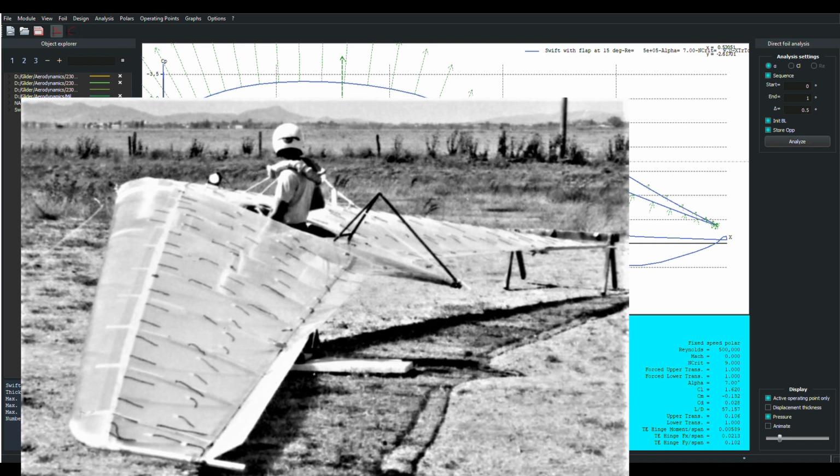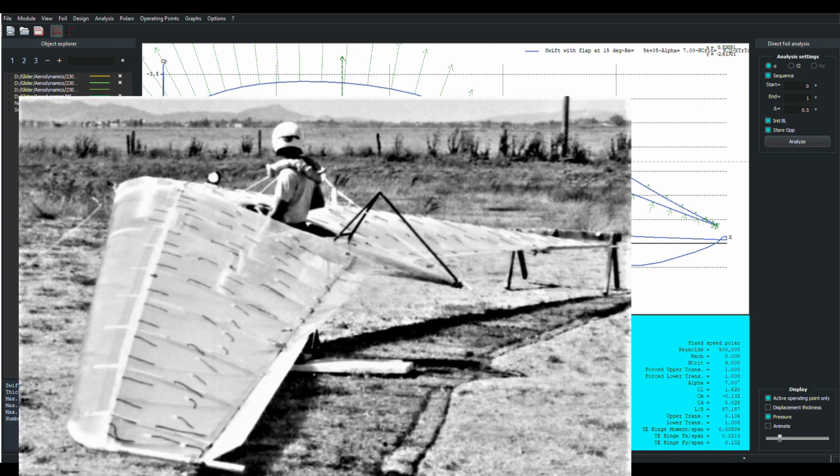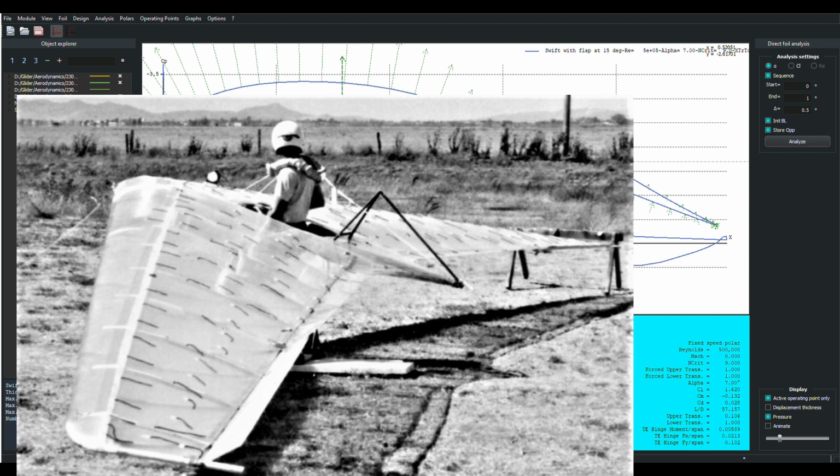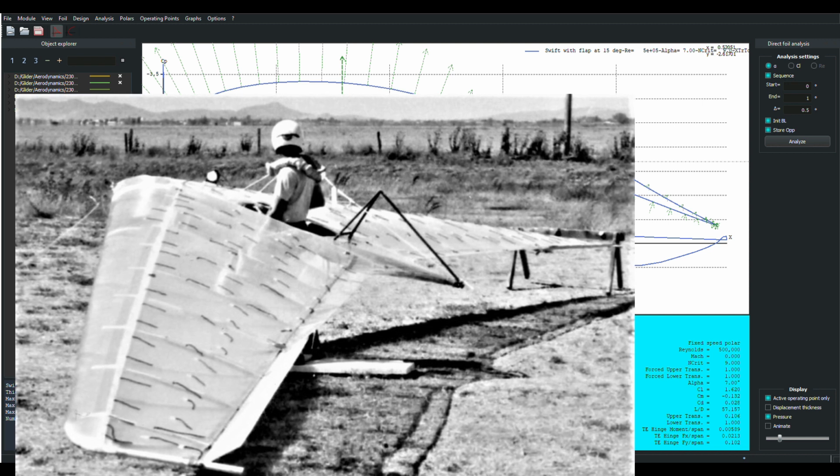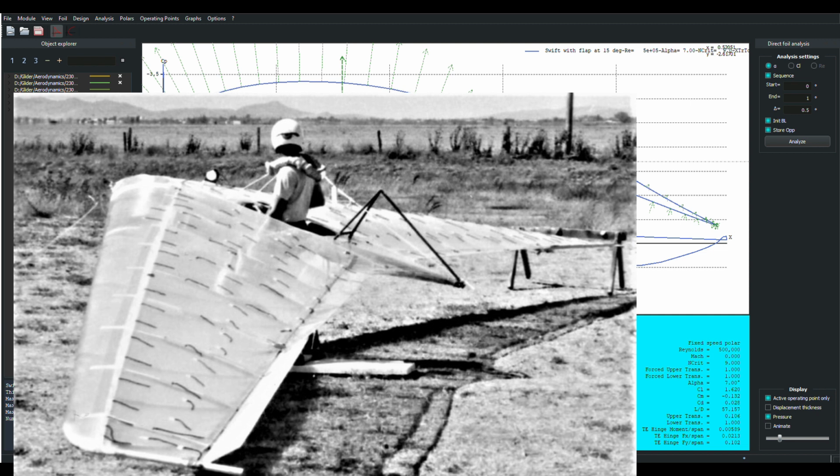And I did that because I'm lazy. I just simply built the elevons flat on my bench and said, screw it. So at the tip end of my elevon, it lines up with the chord of the airfoil. But at the root end, it's actually angled up slightly. So this all had the effect of actually making it more efficient accidentally.